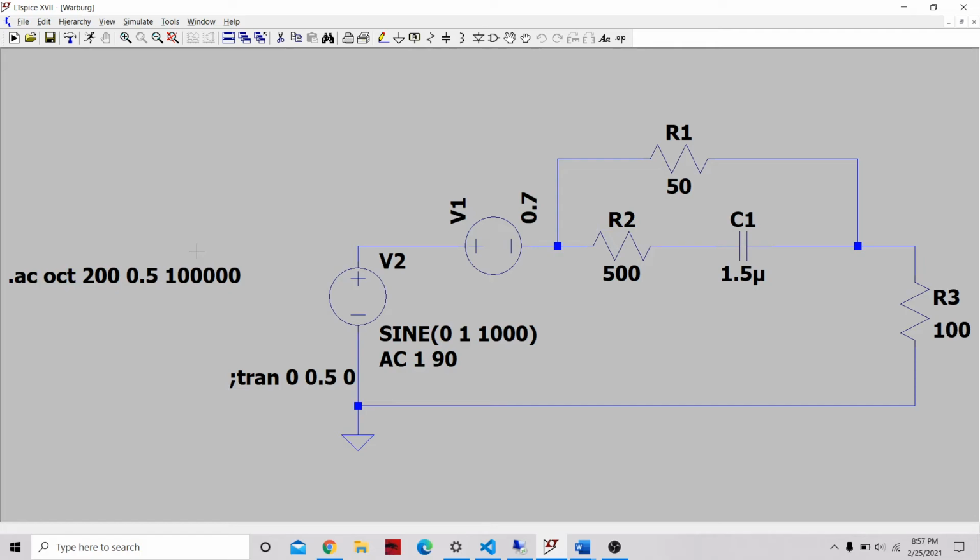You'll start to see this model more and more often, especially as you go into more bioelectronics. This is a model of a tissue-electrode interaction, where this voltage accounts for the half-cell voltage, which is a property of the electrode material, as well as two resistances and a capacitance. I've also added a load resistor here so that we can measure a node. What these are modeling are not important for this lecture, but we'll get more into it later.